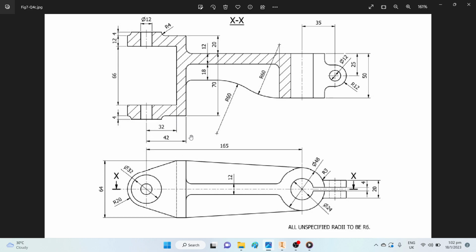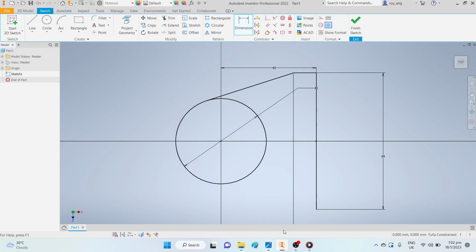Okay, so follow everything according to the drawing, according to the dimensions. Please do not use math to deduce the thickness or the dimensions that you are wanting to draw. And this is a very important point to take note. Alright. Likewise, do not double dimension. What you can do is, you notice I draw the line very far out, and I draw this as well. Double dimension. What is double dimensioning? I'll show you in a very short while what double dimensioning is.